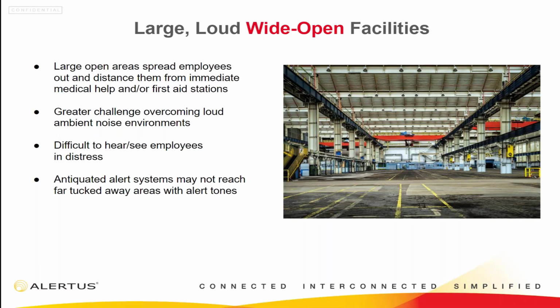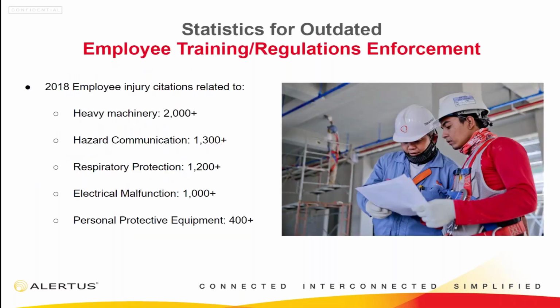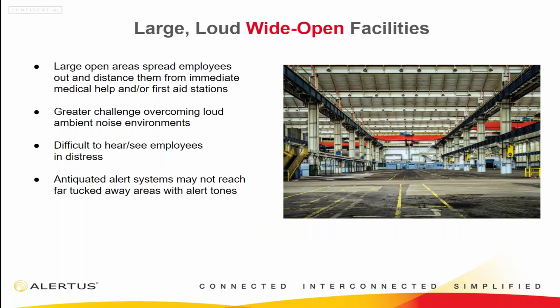One of which might be hazardous areas, where the challenge of that ambient noise level, like we've discussed earlier, may be an obstacle to be able to effectively get that message out. Audible doesn't always cut it, so it's important that we take that layered approach to ensure that we have both a visual and an audible representation of that message to all staff, all employees throughout that facility. We're not always going to have direct access or personal access to those individuals. We need to overcome that with a layered approach and multiple solutions to fit all.